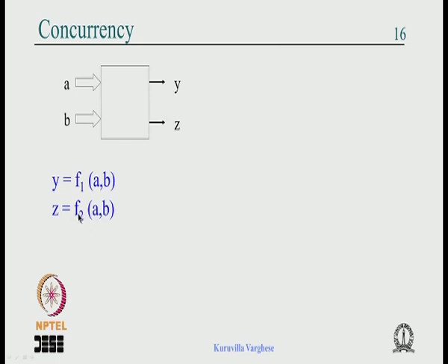But in VHDL, when something changes, both outputs may have to change at the same time. That does not mean you compute at the same time, but that at the same simulation time, when you simulate a circuit, both, being concurrent, have to be computed. That you should keep in mind. VHDL is not like a normal sequential language. Y and Z are concurrent, they are active.